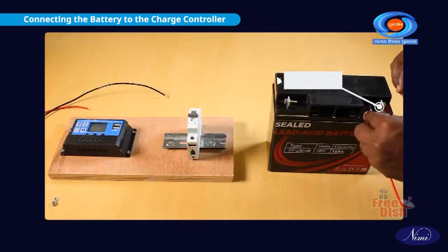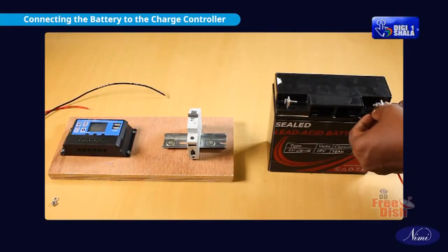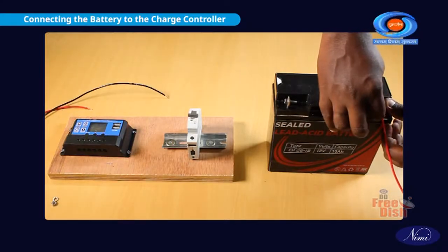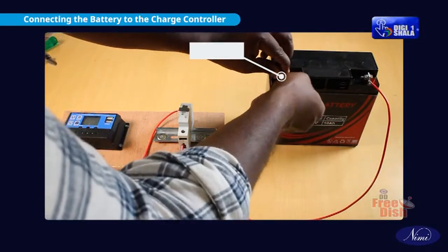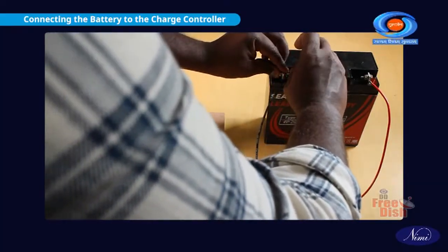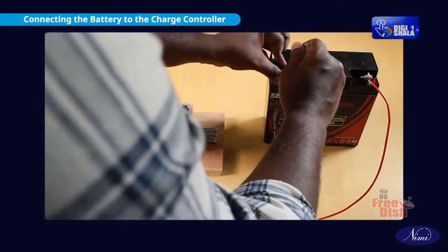Connect the lug terminal of the red wire to the positive terminal of the battery, and the other end of the wire to the positive battery terminal of the charge controller through the DC circuit breaker. Connect the lug terminal of the black wire to the negative terminal of the battery, and the other end to the negative battery terminal of the charge controller. Keep enough tightness using the screwdriver.